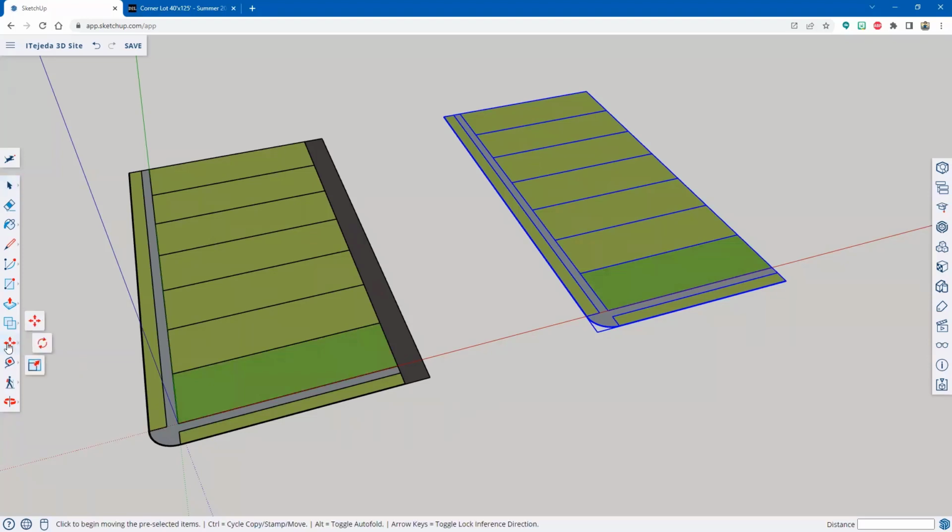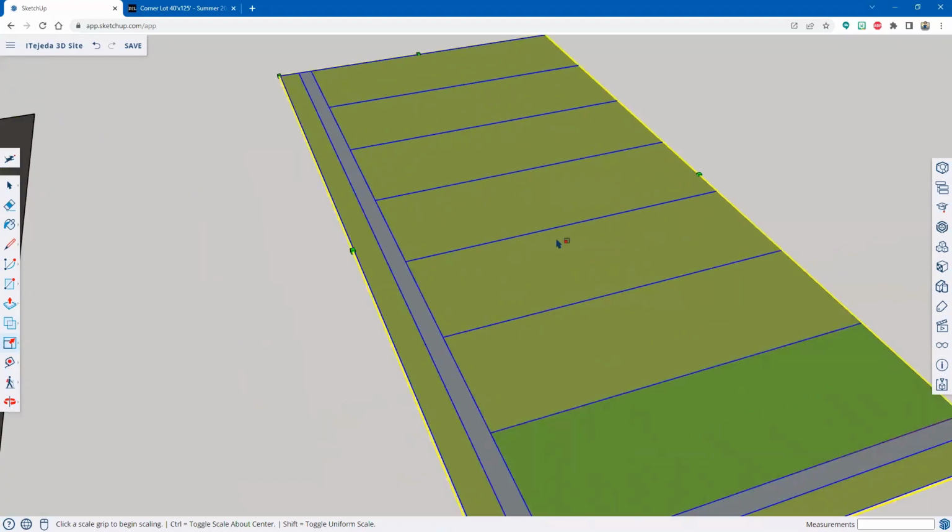forget where it is. So it's underneath the move tool. So here's move, here's rotate, and here is scale. So I'm going to click on scale. And because my group of grouped objects was selected, it automatically creates a boundary here so I can scale this. And you see that there are grip points at the corners and then at the midpoints. I'm just going to zoom in right here like this for a moment.